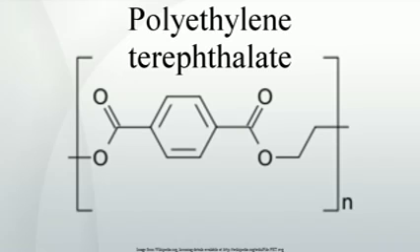Polyester recycling industry. While most thermoplastics can, in principle, be recycled, PET bottle recycling is more practical than many other plastic applications because of the high value of the resin and the almost exclusive use of PET for widely used water and carbonated soft drink bottling. PET has a resin identification code of 1. The prime uses for recycled PET are polyester fiber, strapping, and non-food containers. Because of the recyclability of PET and the relative abundance of post-consumer waste in the form of bottles, PET is rapidly gaining market share as a carpet fiber.